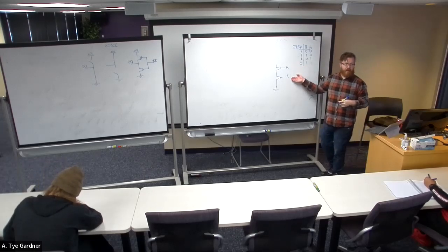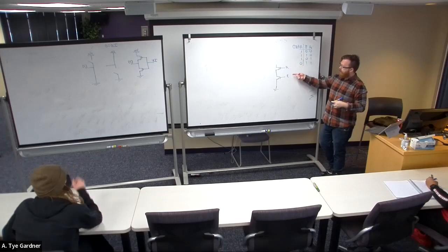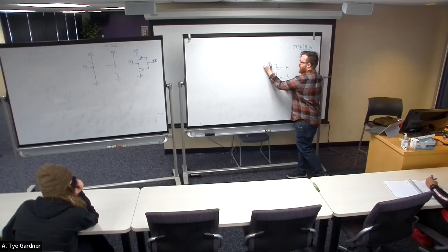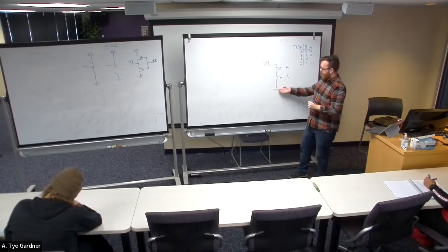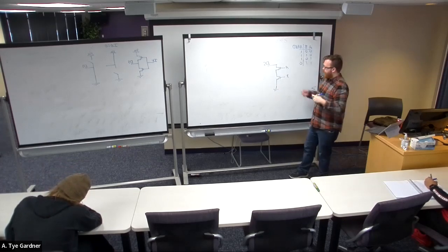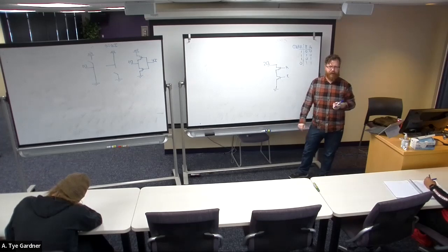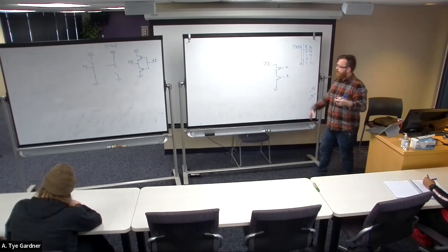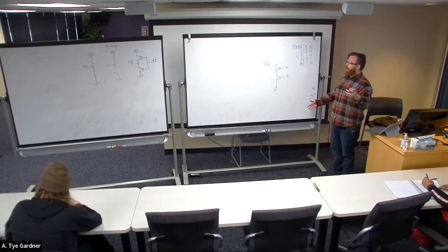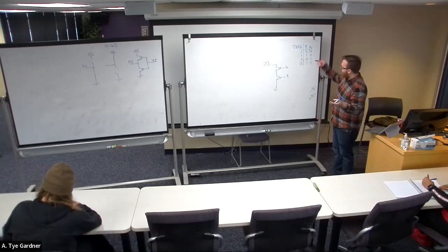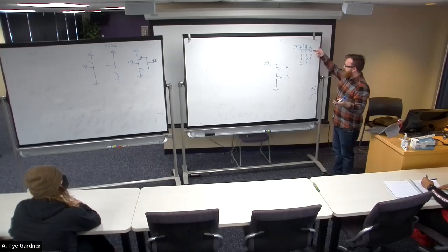In series, if A is 1 and B is 1, then this switch is closed and this switch is closed, and the digital signal is now connected to ground. If either one of them is 0, it is nothing because it's not connected anywhere, right? This is where the pull-up network comes in handy. But the pull-up network is the opposite, which says if either A or B is 0, then I need to pull up.